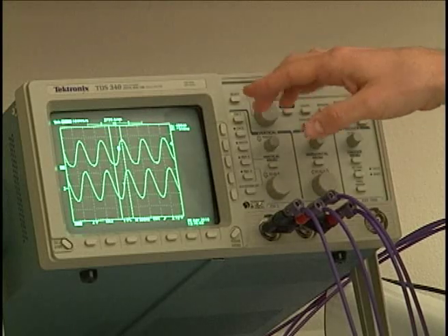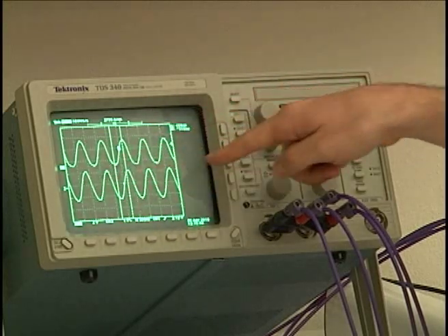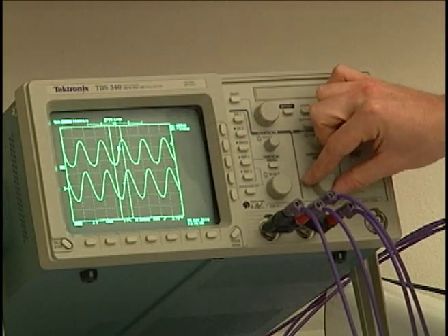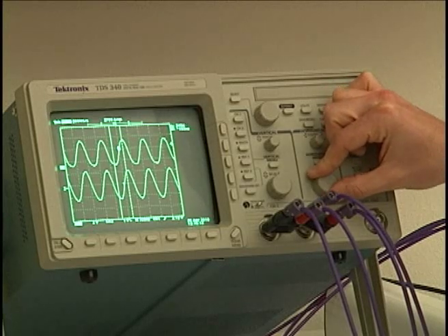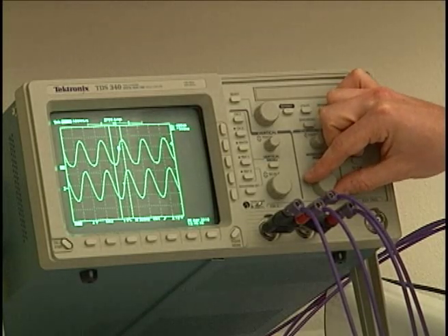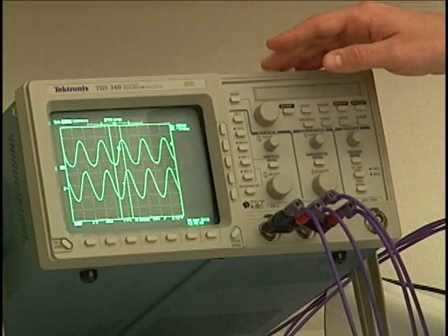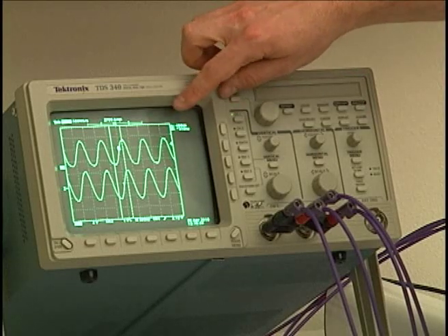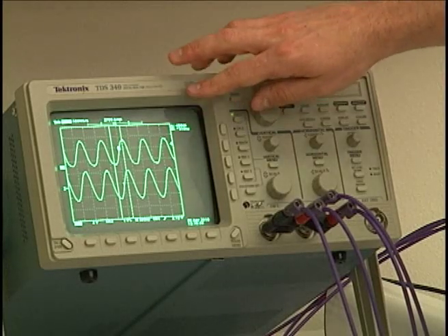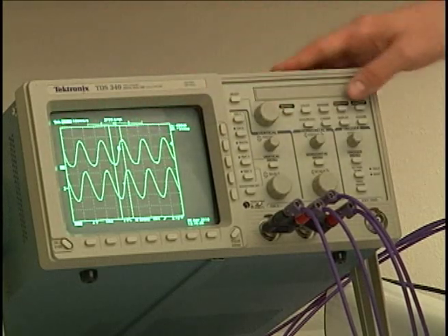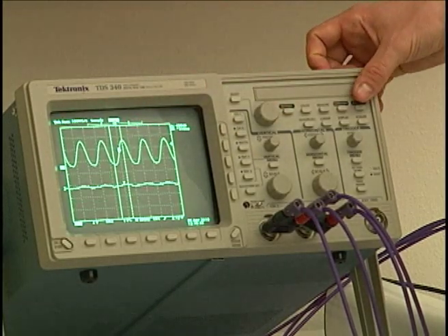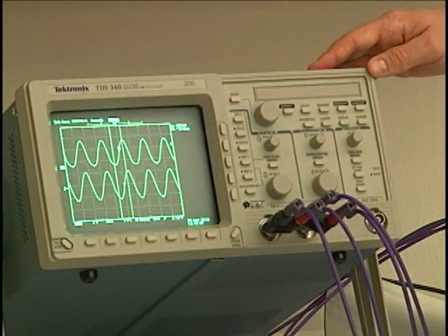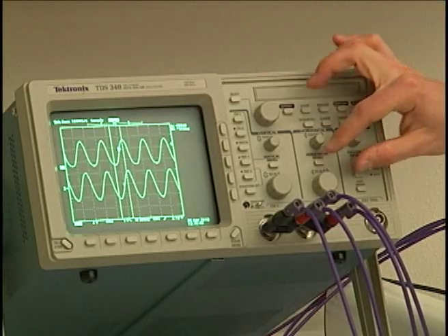So first things first is you want to get the time scale on your oscilloscope to be something that's comfortable for you to read. And you can adjust it with this scale button down here, and you can adjust it so that the waves are going to be either bigger or smaller, but as you can see here, you'll need to do that while you can still run with the signal. So if you do need to go back to the case where these things are varying in time on the screen, just hit the run stop button again and it'll start again. Now you can see this is flat because I'm standing in front of the beam, so when I get out of the way it'll pop back into view, and we can adjust now our time scale.